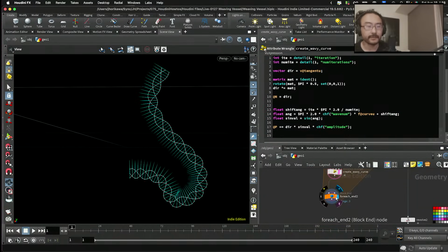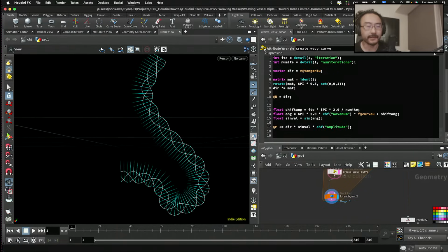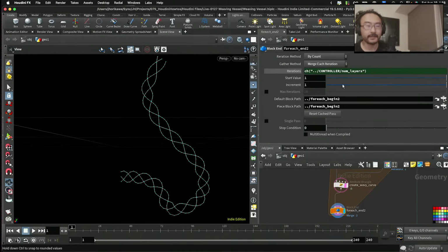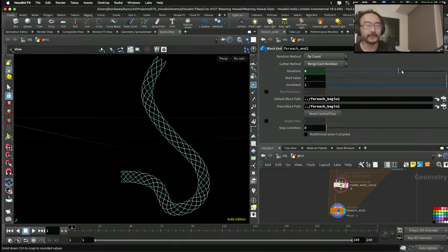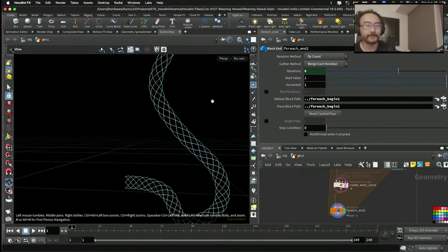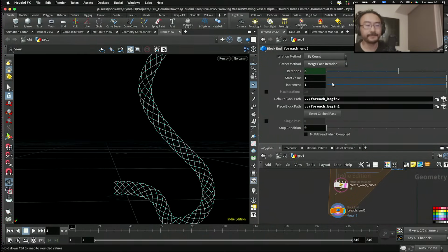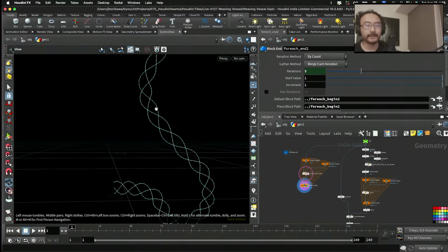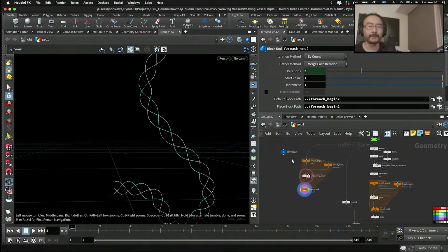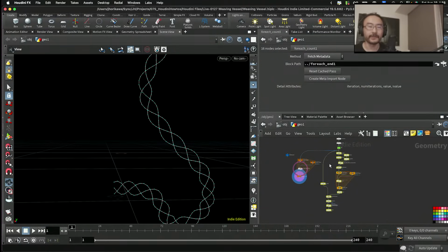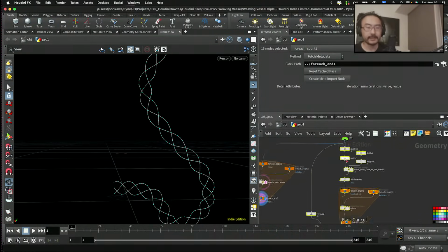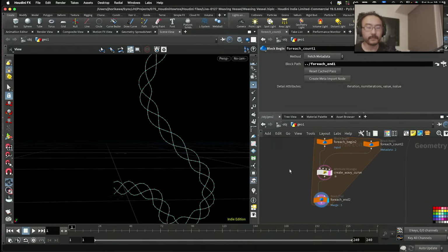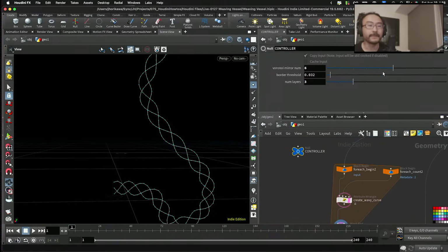Now if you go outside the loop, you get this kind of DNA-like wave pattern. And even if you change the number of loops, the number of layers here, you're always going to get an interlaced result. Alright. Let's try with 3 for now. This is the profile curve that I want to use for each Voronoi surface here. Let's go with a smaller wave number.